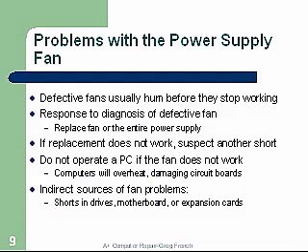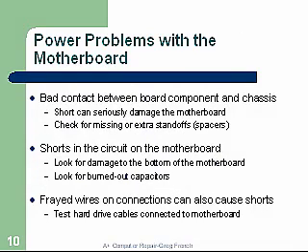Power problems with the motherboard. Bad contacts between the board components and the chassis. There could be a short between the motherboard and the chassis. A short can cause serious damage to the motherboard. Check for missing or extra standoff space, or something might be loose and shorting something. Shorts in the circuit on the motherboard: look for damage to the bottom of the motherboard. Look for burned out capacitors. Frayed wires on connections can also cause shorts. Test hard drive cables connected to the motherboard.